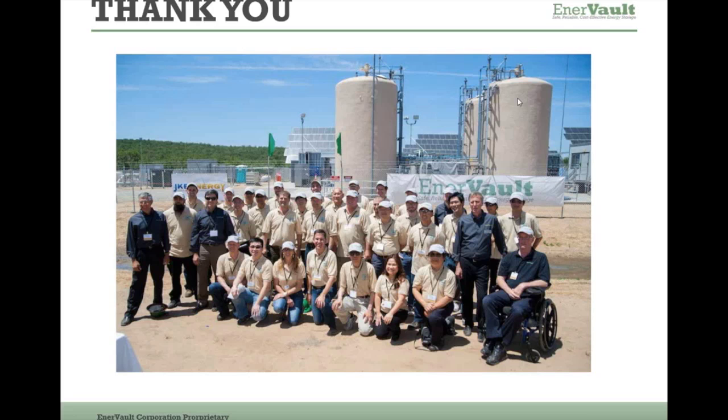A typical rough parameter is that the set of stacks will last on the order of 10 to 14 years. The hydraulic subsystem would be 20 to 25 years. The power electronics are on the order of 10 years. And so we have a comprehensive O&M model to look at the cost that we can match to a specific application. And then, of course, that specific application really speaks to what the payback period would be. But that could be anywhere from 3 years to 7 years, depending on the application and the specific parameters around it.